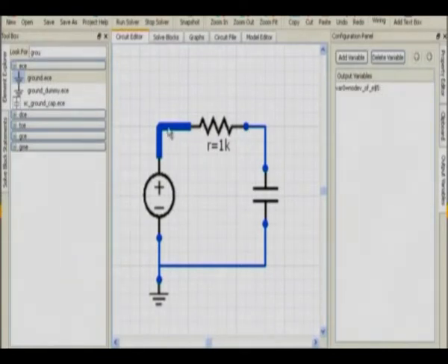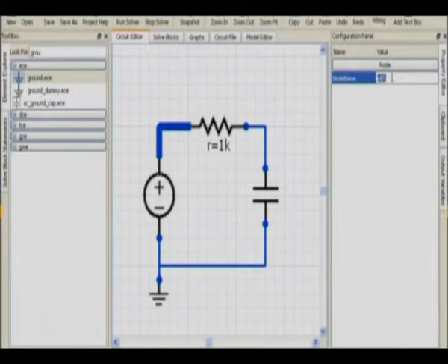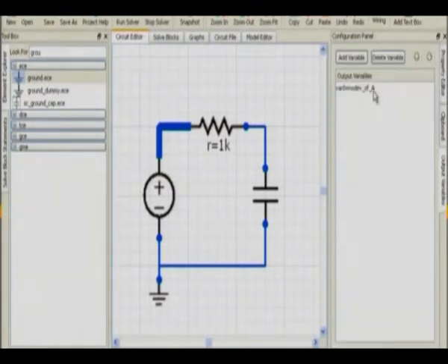So that something something is the name of this node. This node name can be changed. For example, I can select this, I can go to the property editor, and I can make this A, for example. All right. So then in that case, this will automatically change in the property editor. I can also change the name of this variable, and in this particular case, it makes sense to call it VA, for example. All right.